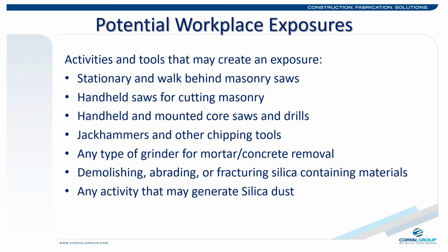The following activities and tools may create an exposure and are commonly found on construction sites: stationary and walk-behind masonry saws, handheld saws for cutting masonry, handheld and mounted core saws and drills, jackhammers and other chipping tools, any type of grinder for mortar, concrete removal, demolishing, abrading, or fracturing silica-containing materials, and any activity that may generate silica dust.